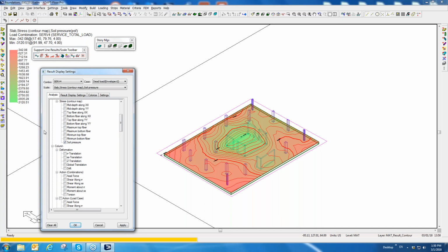So you can see along the path, we've done 4 different runs. We've done tributary axial only, which was 3275. When we did substitution, we had, let's say, 3466, and then the direct solution we have 3122. I would not expect the same solution in each run, because we're changing the behavior, we're changing some modeling and analytical assumptions when we run each one of those unique solutions.